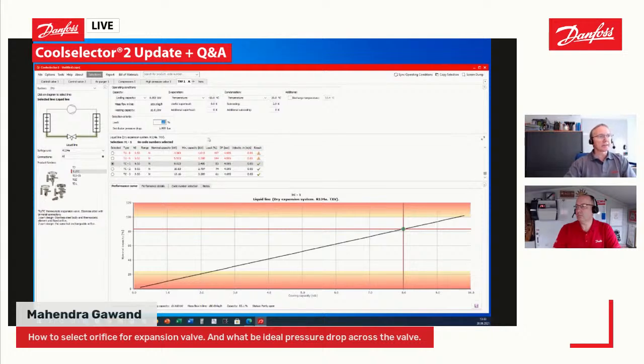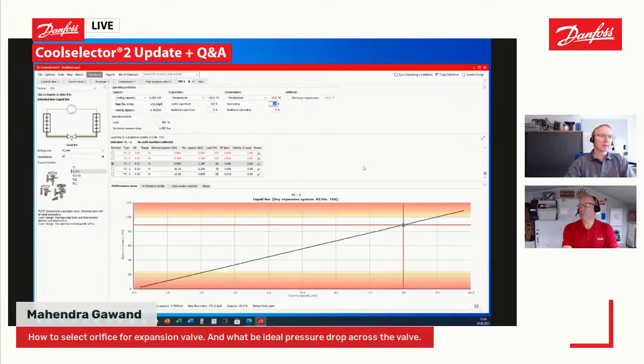And another one is when it comes to summer and winter conditions as the extremes. This is my recommendation: if you go to select a TXV, always look at both scenarios, summer and winter. How to do that? You may have set up your system to run at a minimum condensation temperature of 25.